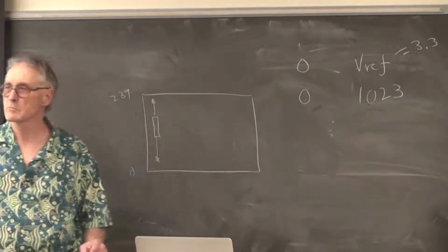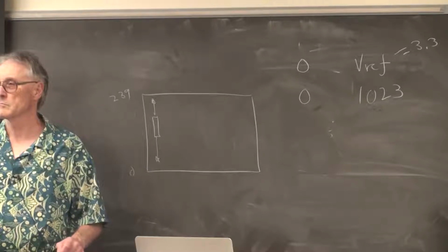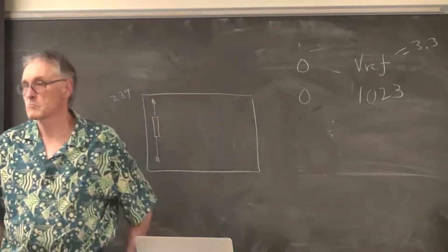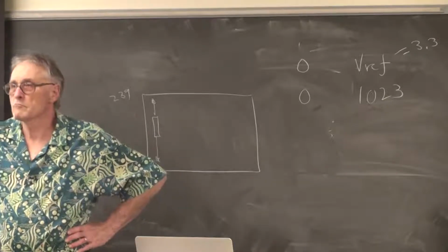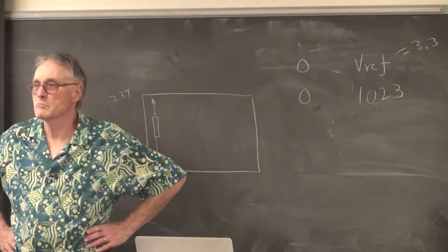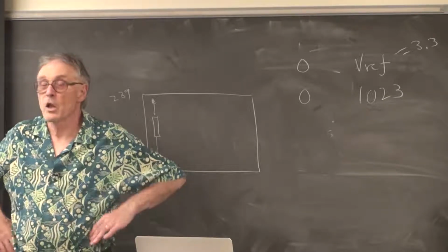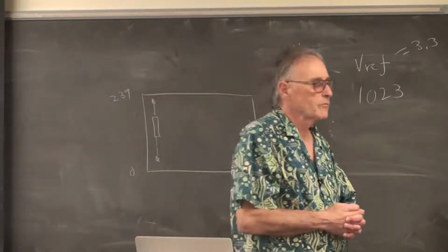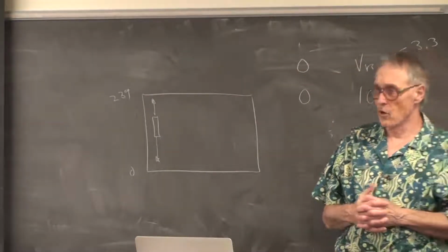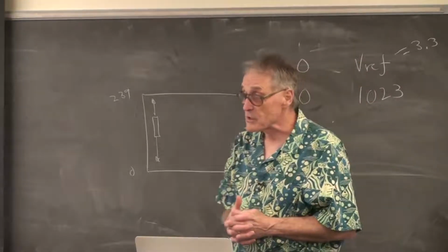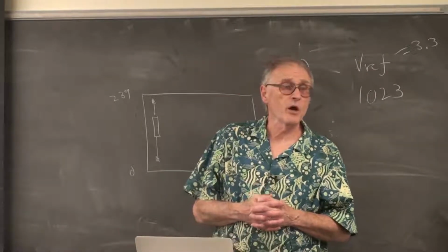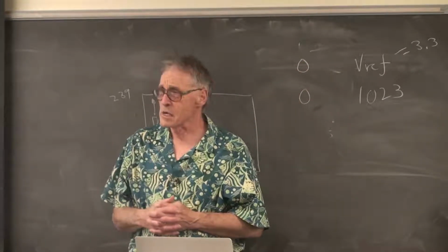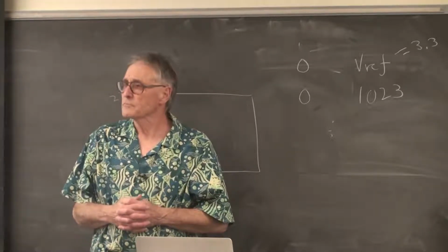As far as drawing on the screen goes, I've noticed that when you clear the screen and then write stuff to it, it visibly flashes black when you write over it in black. Is there a good way to clear the screen and redraw everything without having that effect, so that we can have smooth looking video? So the question is, how do you avoid clearing the screen to black before you redraw everything? Because that's a slow operation. It has to redraw 320 times 240, which is a little over 70,000 pixels. The answer is don't do that.